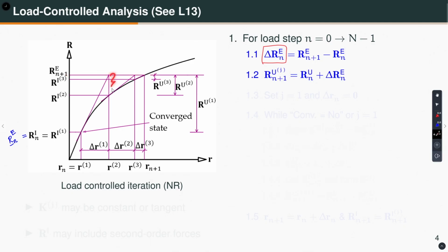So, there is an error. So, this is the equilibrium error or the unbalanced force at the end of the second iteration. When we started this load step, then this entire thing was my unbalanced, right? So, it has reduced. Now, at this point, I again determine the new tangent stiffness matrix, okay? So, that means I am going like that, right? And then this is my new displacement.